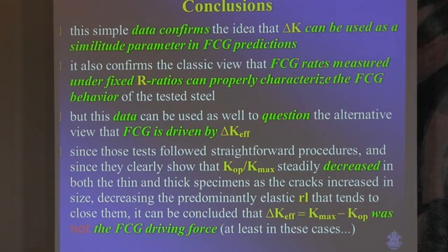Conclusions. Very simple and easy reproducible data. It confirms, thank God, that we can use delta K as a similitude parameter in fatigue crack growth predictions. I can correlate the da/dN with delta K. Very happy with that because I know how to calculate delta K.